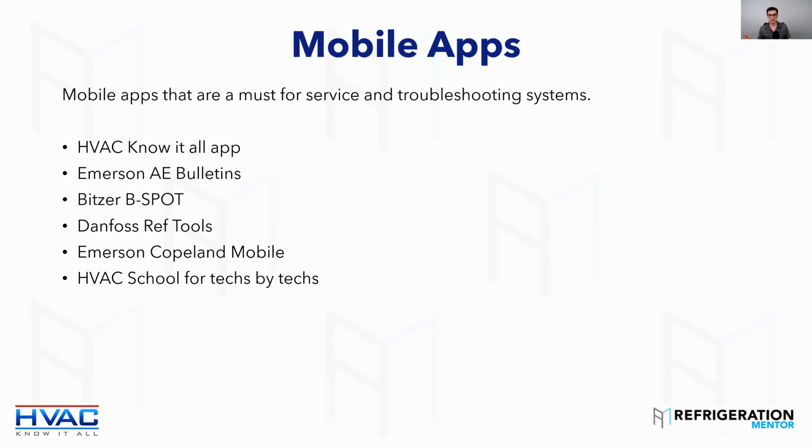The Bitzer BEST-Spot app, another great app if you're working on Bitzer compressors. It has all their documentation in there. Copeland sells semi-hermetics, Bitzer sells semi-hermetics. Semi-hermetics pump the same way, they work the same way, but there is a lot of uniqueness to each. I'll give you one quick example. Copeland under semi-hermetic says they don't like to see the discharge line temperature, 6 inches from the discharge, higher than what temperature?